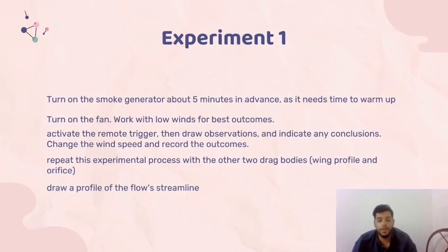Okay, now we're working with the procedure of the first experiment. First of all, please turn on the smoke generator for about 5 minutes in advance as it needs to warm up. Then turn on the fan, and work with low winds for the best outcomes.